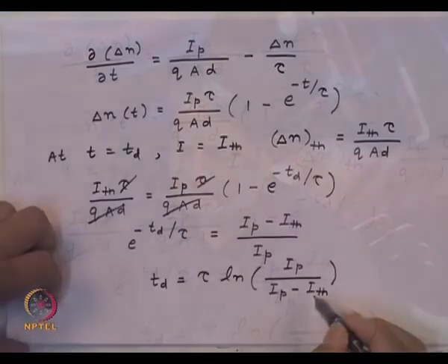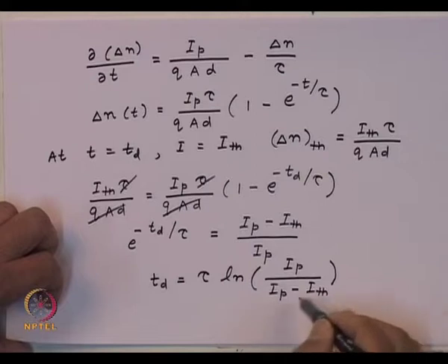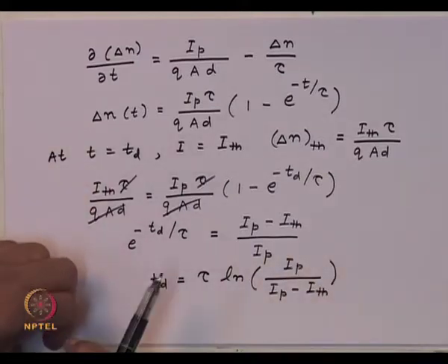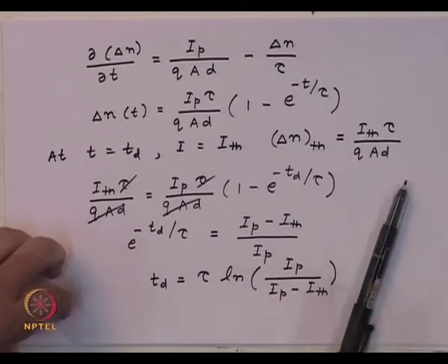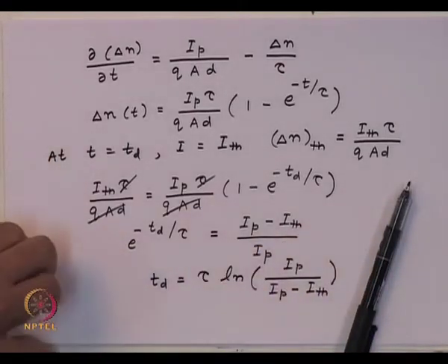So, if you wanted to modulate it at a faster rate, you will not be able to, because this much time is required to get the laser into action. This parameter essentially tells you about the speed of the device, or the modulation speed which the laser would have. If the threshold current is large, then this quantity will become smaller and smaller, and the speed increases, but this quantity essentially goes down.